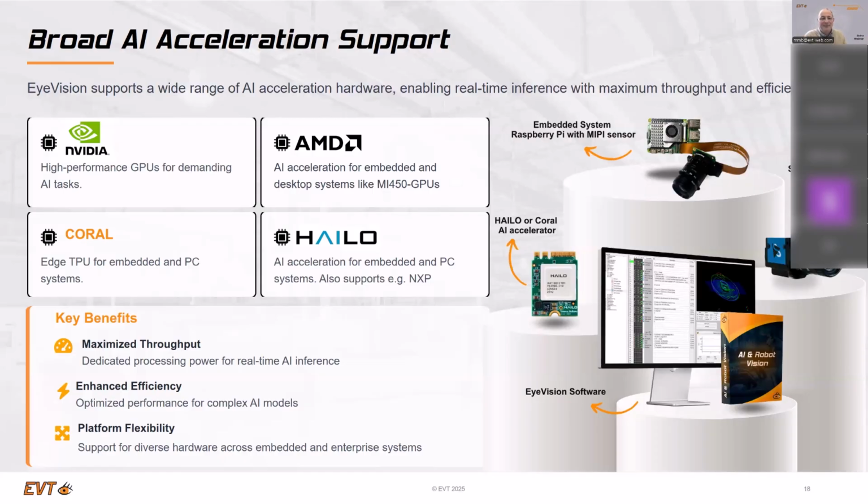So simply consider, if you select these special sensors, besides that you can use them with your software, that you need a special light and a special lens also, to have the right transfer function. If you have a very high resolution sensor, you need a lens which fits to the high resolution sensor.